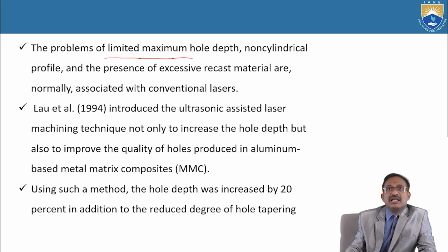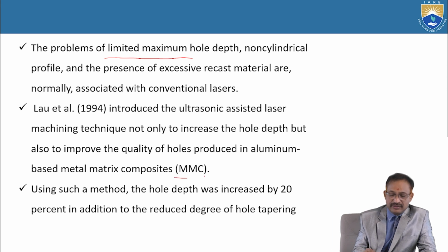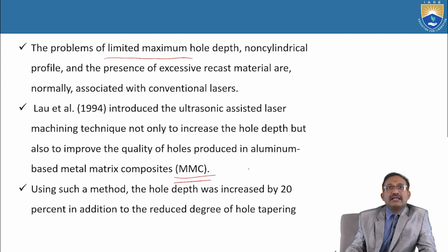Lau et al. during 1994 introduced the ultrasonic assisted laser machining technique not only to increase the hole depth but also to improve the quality of holes produced in aluminum based matrix composites. So here, metal matrix composites with aluminum. The focus is not only on the depth of the hole but also on the quality of the hole production.